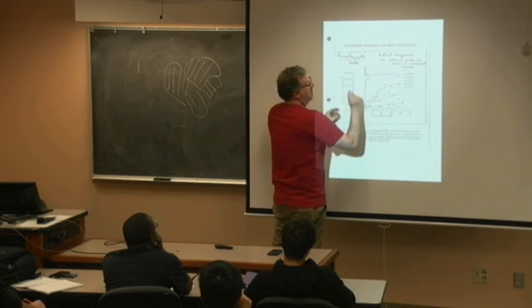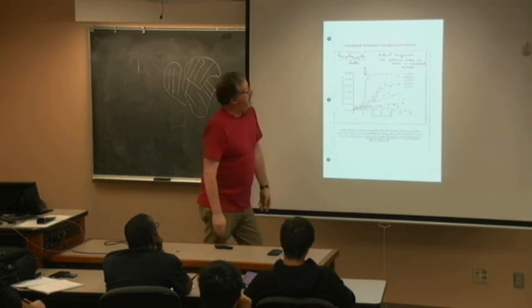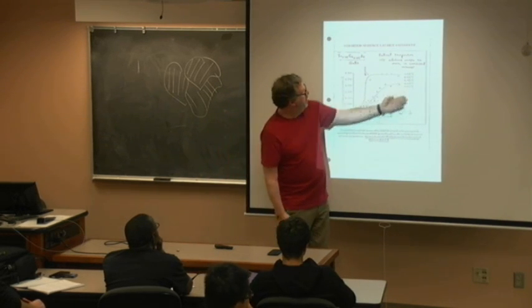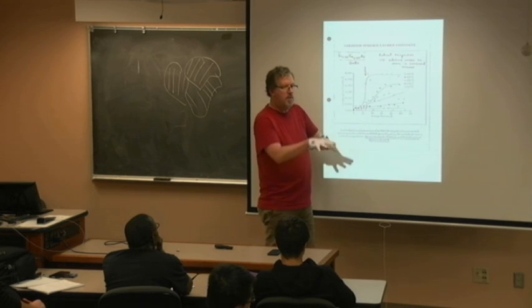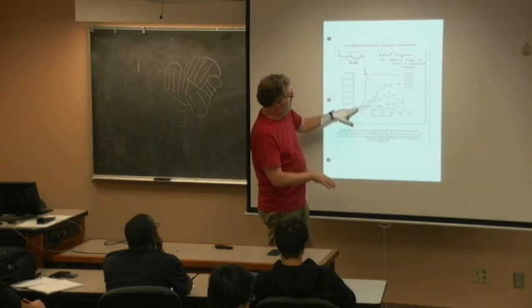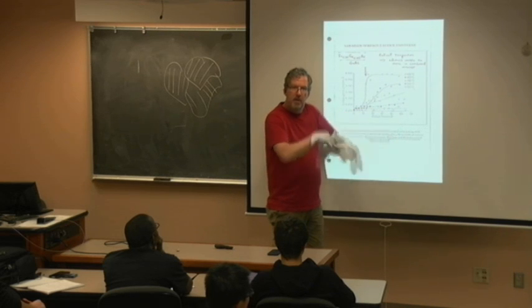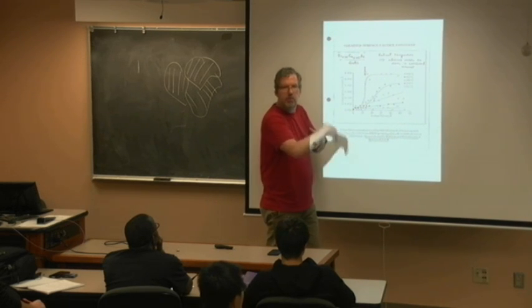I could actually see this pop. And I could freeze it in because of temperature and time. If I made it cold, I slowed down the motion of the atoms and it delayed this. Now if I heat treated it later, it would pop into place. They're just waiting for that energy.